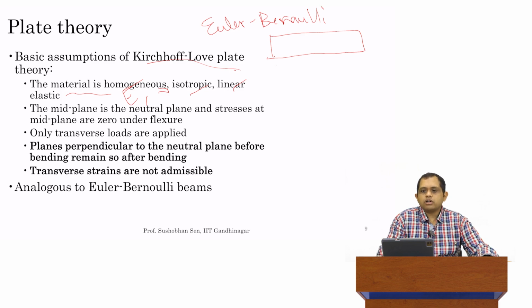What we know is that when Euler-Bernoulli beams, for example, a simply supported beam, are subjected to some load, they undergo some amount of displacement. We know this. One of the basic assumptions we make is that we have some sort of a plane, and that plane, at least for plain concrete, goes exactly through h over 2, so through half the thickness. Our basic assumption is that at the neutral plane or the neutral axis for a beam, the stress remains 0.